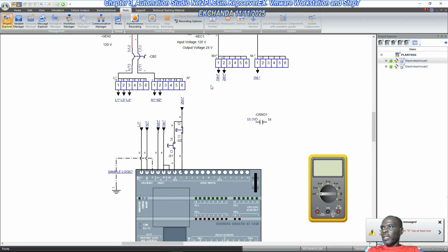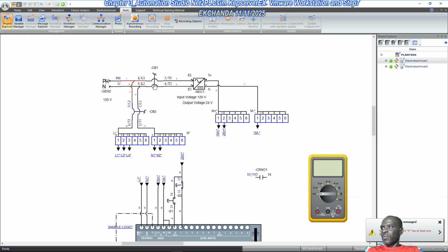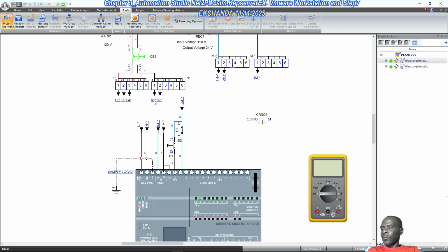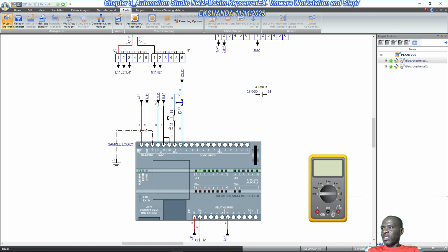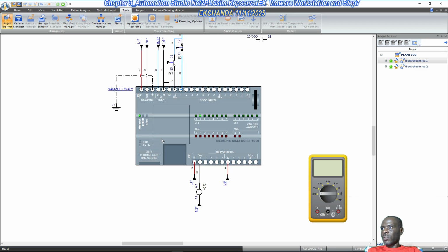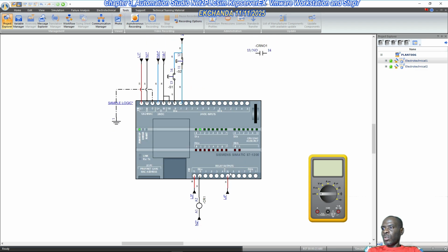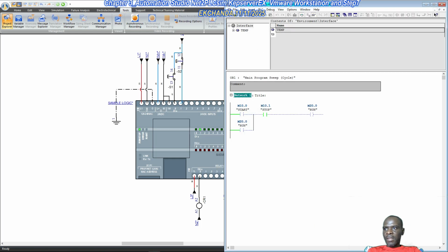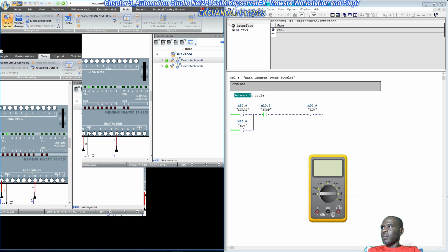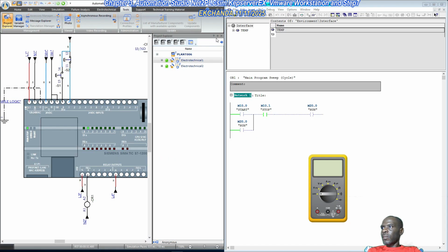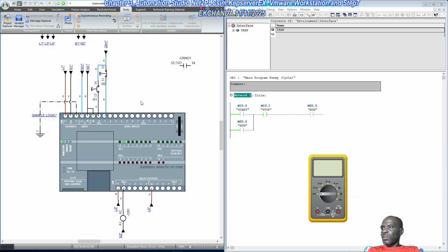So now that we're running, we need to close the breakers for the rectifier, and then the live AC for control. Okay. So rectifier closed, energized, and the AC for control, or rather for the supply of the PLC, has also been closed, the breakers. Okay. So now we have this. So I'm going to put this next to step 7. Okay, I'm going to put them side by side, like so. Won't be needing that. So this is what we have.